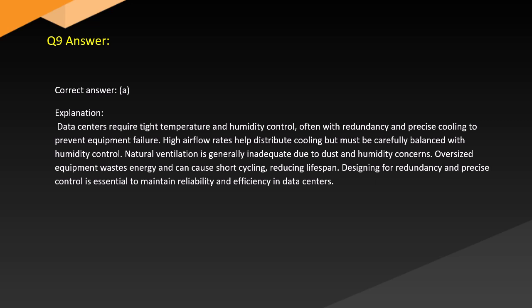Natural ventilation is generally inadequate due to dust and humidity concerns. Oversized equipment wastes energy and can cause short cycling, reducing lifespan. Designing for redundancy and precise control is essential to maintain reliability and efficiency in data centers.